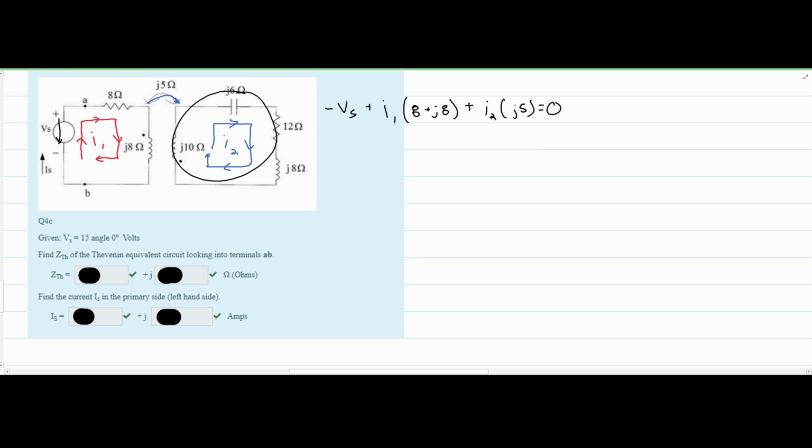Now we're going to look at the second part right here, and we are going to find the voltage for it. We're going to use the same formula. We don't have any voltage in here, so we are not going to have some V of S. But what we are going to have is our I2, and inside of our I2, we add all of the impedances together. If we add, we have this 12 ohm resistor, and then the rest are in J, so they're imaginary numbers, they're either inductors or capacitors. We add all these together, and this gives us 12 plus J times 12.